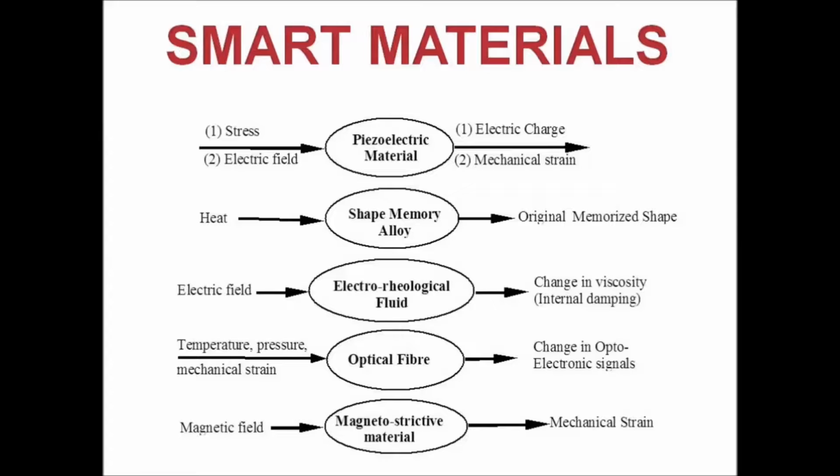Now these are the smart materials and the associated direct effects and converse effects, that is all the stimulus response relations. Piezo materials: if we provide a stimulus in the form of stress, we see the development of electric charge. Conversely, if we apply an electric field, we see the development of mechanical strains. So these are the stimulus response features which make piezoelectric materials smart materials.